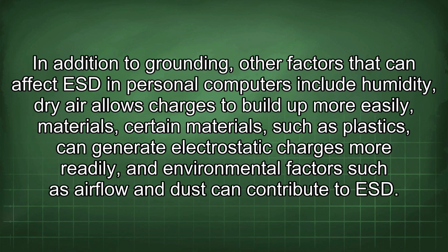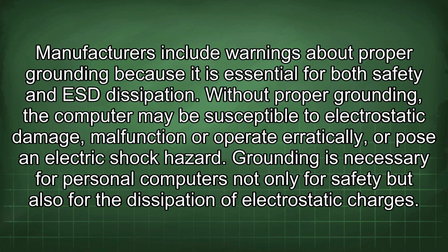In addition to grounding, other factors that can affect ESD in personal computers include humidity. Dry air allows charges to build up more easily. Certain materials, such as plastics, can generate electrostatic charges more readily, and environmental factors such as airflow and dust can contribute to ESD. Manufacturers include warnings about proper grounding because it is essential for both safety and ESD dissipation.